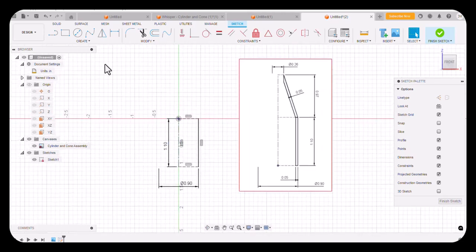I'm then going to draw a line, and I'm going to draw it horizontally from this point over here. And that symbol right there tells me it's going to do a perpendicular constraint. Maybe if I scrub this line, well, sometimes it will do a collinear constraint. I'll come on down, and I want this perpendicular, so I'll come down, and I'll try scrubbing this time and see if I can see that tracking line.